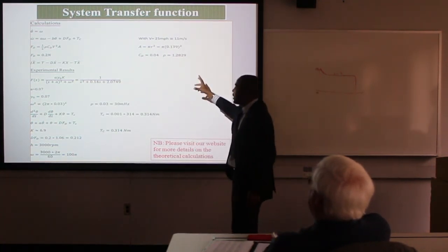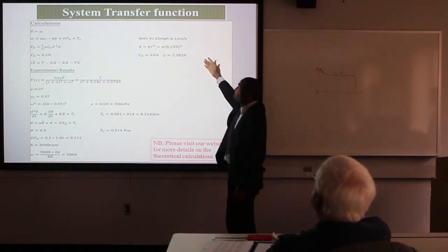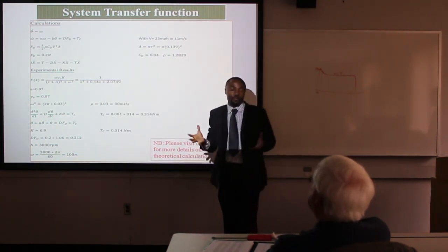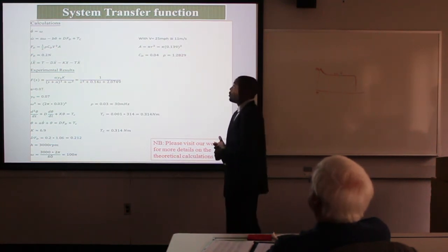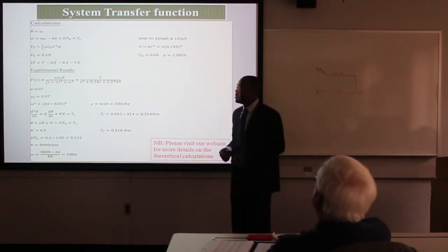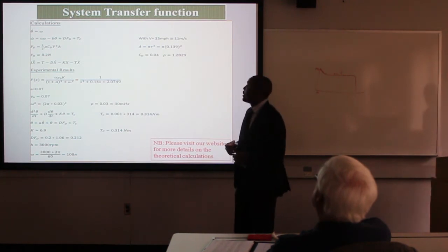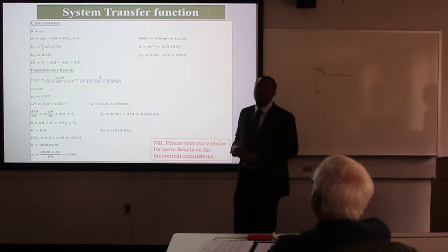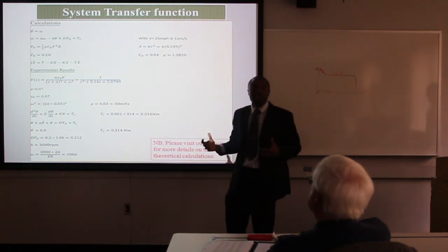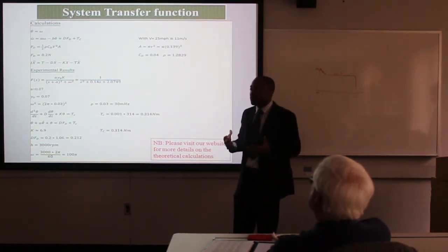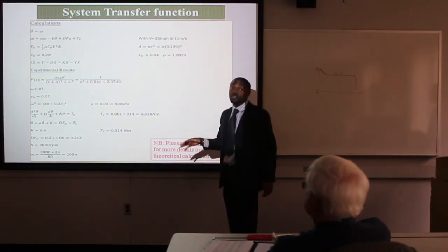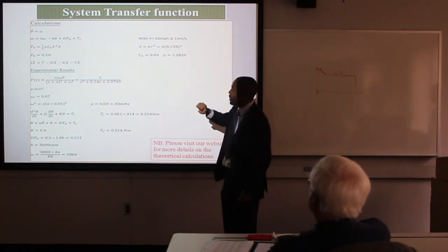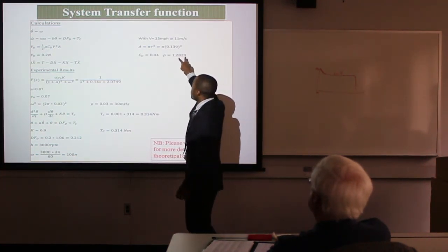Once we got that transfer function, we had to calculate and simulate the force that was attacking the turbine. We used a wind speed of 25 miles per hour, because our turbine starts to build stable power at 25 miles per hour. If you want to design a system for a region where you think the wind can be greater, you can just change the value and calculate the force that is going to attack the turbine.